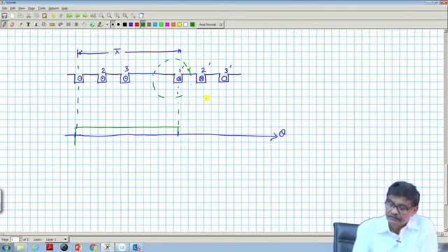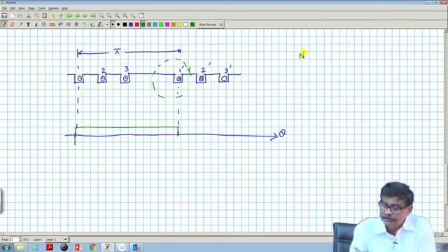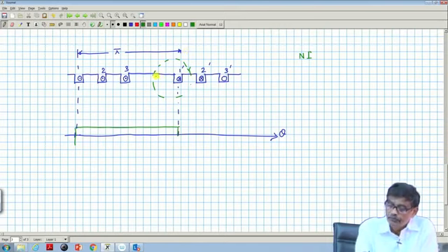This is the thing. So, how much is the MMF enclosed by this path? If it is a multi-turn coil, Ni is the total MMF acting in the circuit, apply that circuital law of magnetism. This MMF will be dropped in the 2 air gaps, and Ni by 2 will be the MMF in each path.